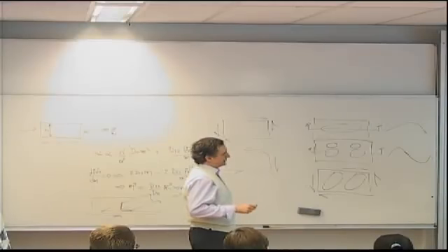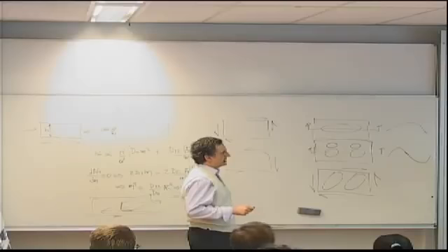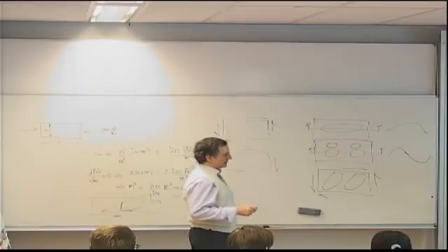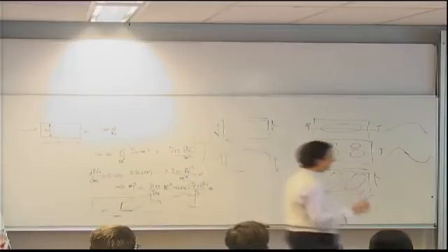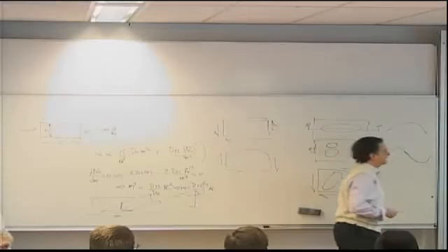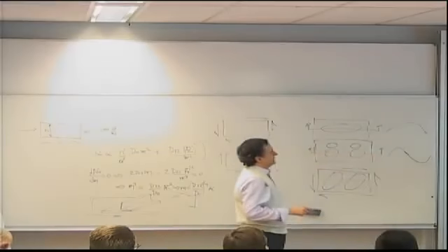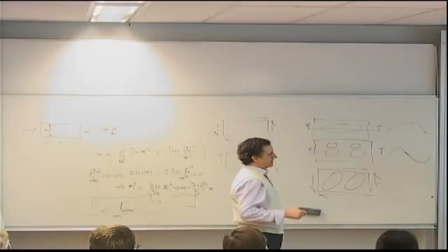this expression will satisfy my displacement boundary conditions. W is 0 everywhere all around the edge because these sines are 0 at x equals 0 and a and 0 and b. And it so happens that it also satisfies my force boundary conditions.